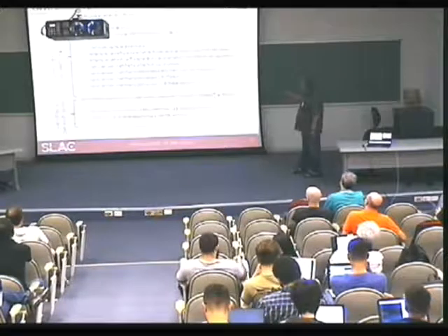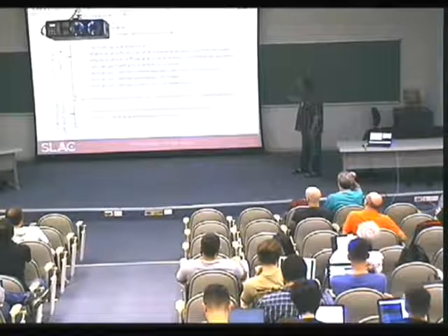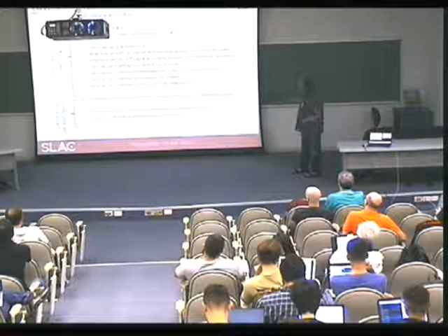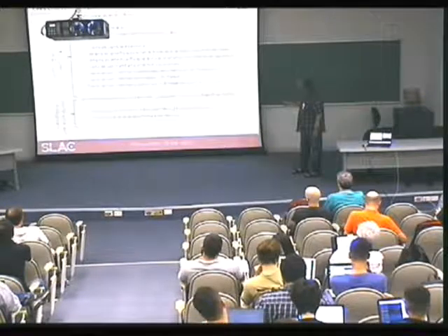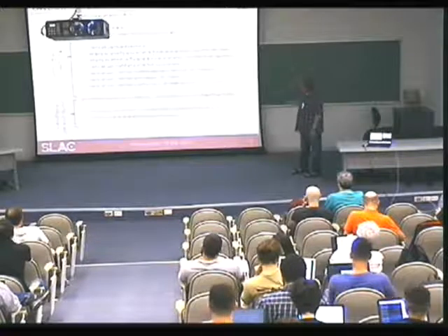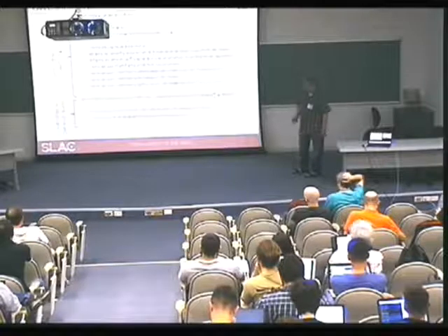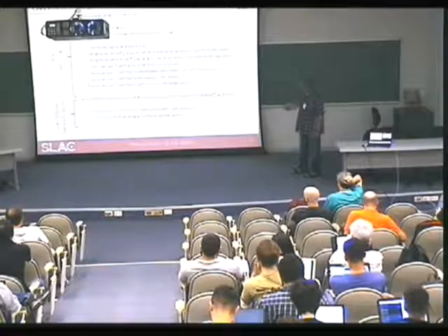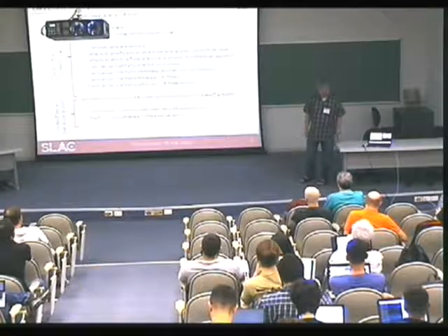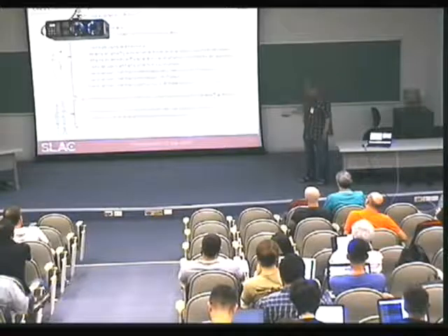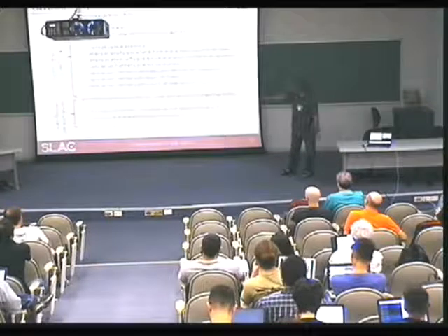And you may say, by default, it is gamma. And by default, the particle goes toward the Z direction. By default, the energy is 100 MeV. And by default, the position of the vertex is 0, 0, minus 50 centimeters. So these are defaults. Of course, you can change them by UI command before you start the run. Change the particle if you like, change the position if you like. Now, here the generate primary method is invoked per event.